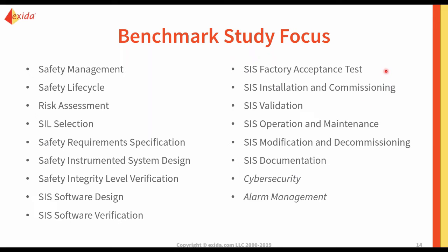Also looking at factory acceptance tests, so the way through the installation, commissioning, validation, all of the steps of really implementing the safety system, as well as the requirements for the SIS operation and maintenance, so what the proof testing is, how that's carried out, the management of change, so looking at SIS modification, decommissioning, the SIS documentation, so having clear traceability of all of those requirements and the outputs of each step.